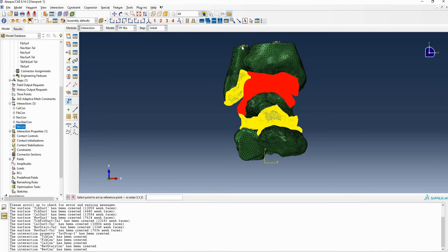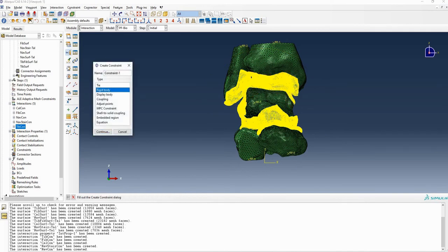So you can click, define one reference point for each bone. Okay, here let's rotate it a little bit. It's heavy. That's why it's a little bit slow. After you created the reference points, next you can create a rigid bone, and you change the name.